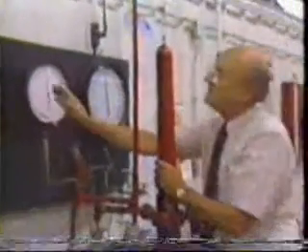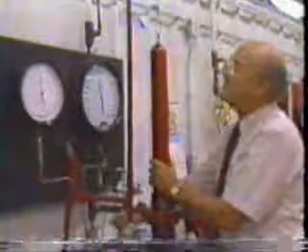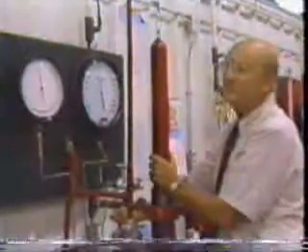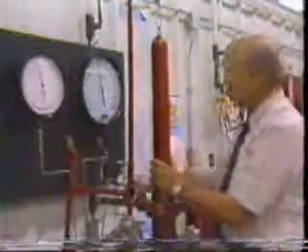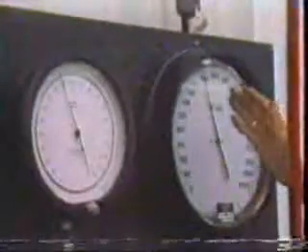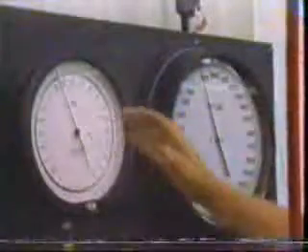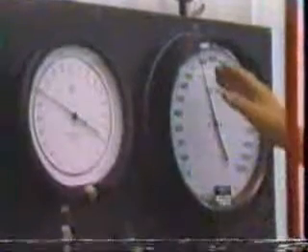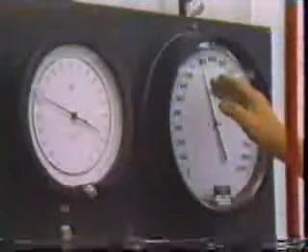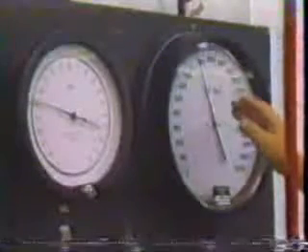Now watch both of these gauges as I slowly bleed the pressure from the tubing side of the valve. The valve is open. As I bleed pressure from the tubing side, we lose pressure in both the tubing and the casing. Watch how the gauges fall together. Wait, this one's falling faster, so I stop the bleeding. This one has stopped at 840 pounds. That describes or defines the valve calibration pressure.